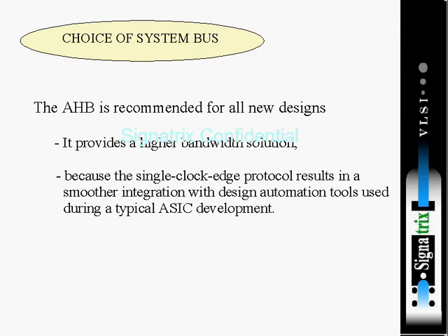You can choose this AMBA-AHB. It provides a very high bandwidth solution. And second is, because a single clock edge protocol results in a smoother integration with the design automation tools used during a typical ASIC development. Yeah, generally there are two kinds of simulators: event driven simulation and cycle driven simulation, right?